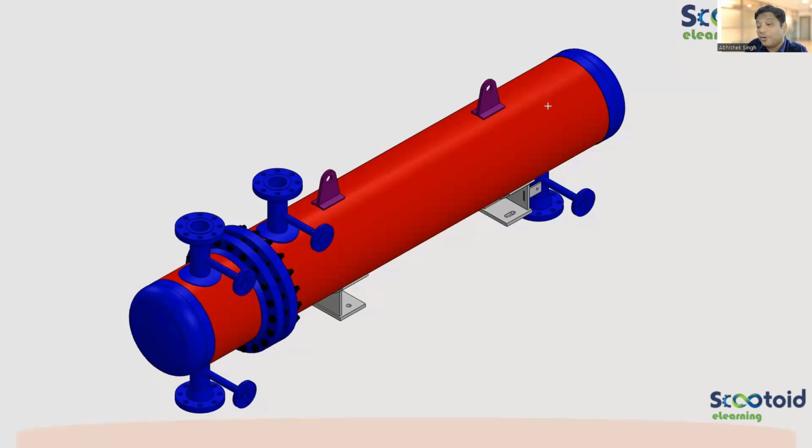The other tube sheet you will not be able to see from outside, but there are flanges connected at this point. There is a flange, and this second part becomes a little bigger. The shell is larger than the previous shells to accommodate the floating head. The second tube sheet is small and goes inside the channel cover.